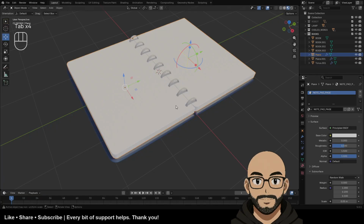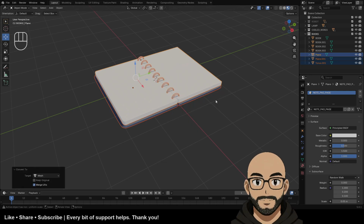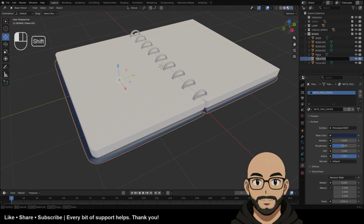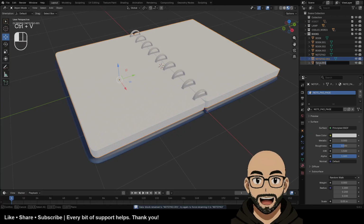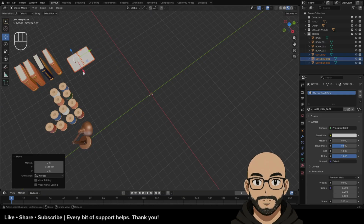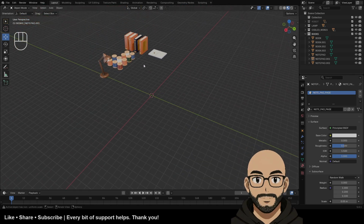And what I'll do is actually convert this to a mesh, so all these modifiers will be applied. And now the modifiers are applied. And then we can name these parts, or we can just name them. I'll go notepad. Then it will do notepad 1, 2, 3, for example, just for now. Control C, notepad. Control V, notepad. There we go. And we have a notepad. And of course, I can select this all and move this. There we go. And we have another asset built.